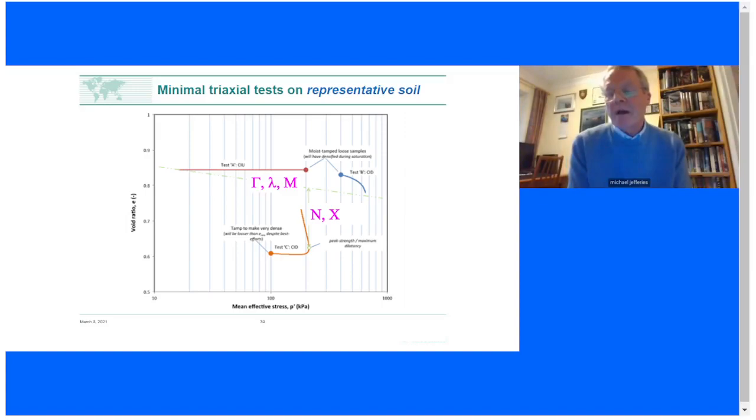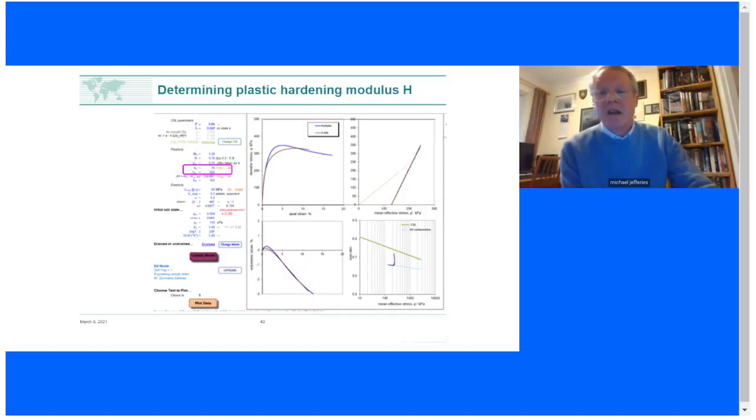If you look at these failure investigations of dams that failed, typically we will pick a characteristic gradation, or an average gradation, and then we'll take a step out fine gradation and a step out coarse gradation. So we commonly will repeat this process for 3 characteristic or 3 representative soils.